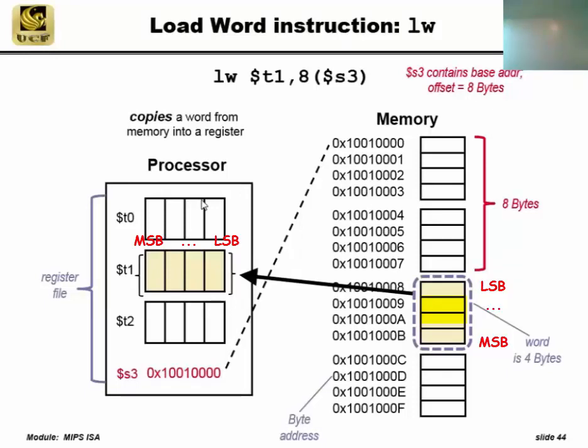Going down, how are these bits transferred? This byte, then this byte, then this byte. Where do they go? Good question. That comes over to this least significant byte here. Why is that? Because we want to represent a number. This is the 31st bit place. This is the 0 bit place. Why? Because MIPS is a 32-bit word. Can you see those bits? Yeah, we're going to actually look at it. We drew a diagram, but we'll actually look at a real chip and show you how to design these.